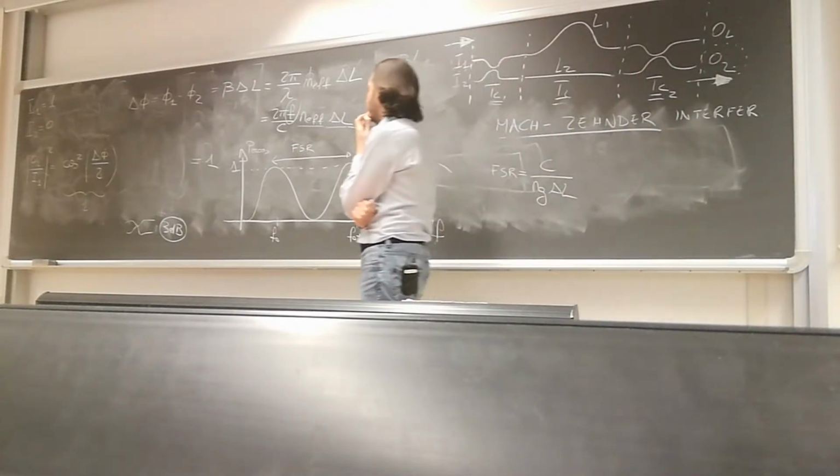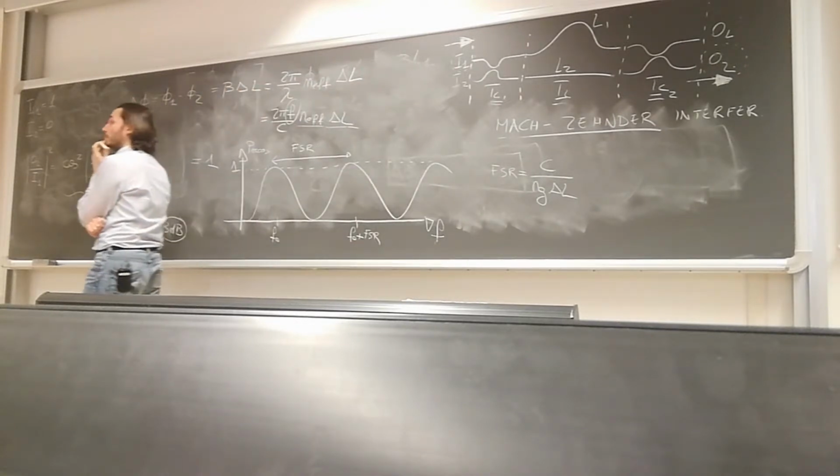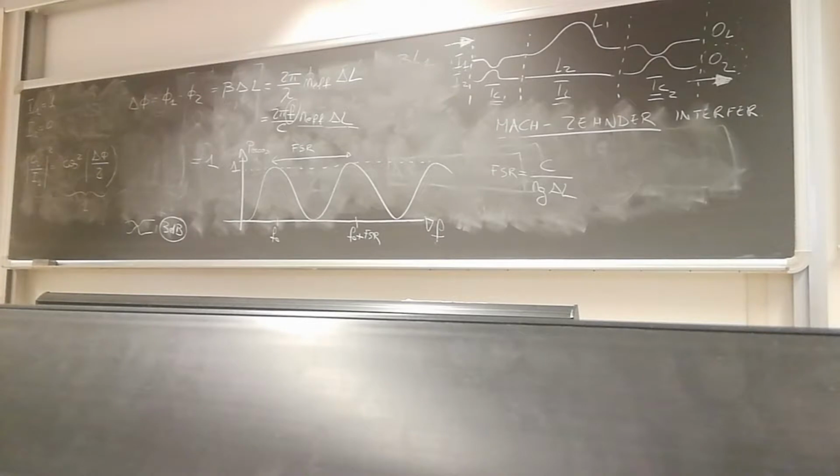Two-mode waveguide means that I have an input signal at a frequency f. So the frequency is defined from the source, from the laser. Okay, so it's f for both. The difference is that if I have a single mode waveguide, all the power will travel in the waveguide with the shape and with the properties of a single mode. Yes, but only one mode.